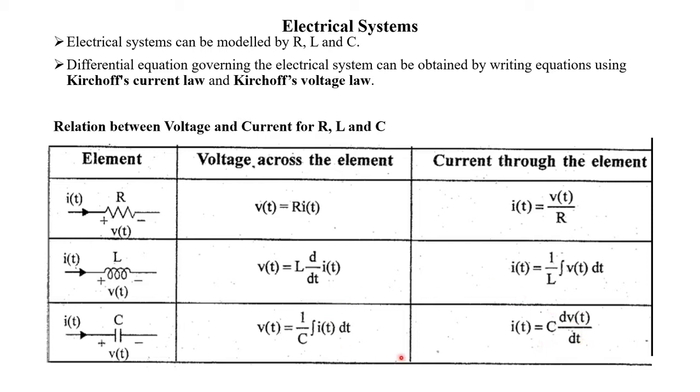Here you have to remember that while writing the voltage, for the inductor you will get a differentiation, and for the capacitor there will be an integration. While writing the current, it will be the opposite. That is, for the inductor there will be an integration, and for the capacitor there will be a differentiation. All these are formulas that you have to study.